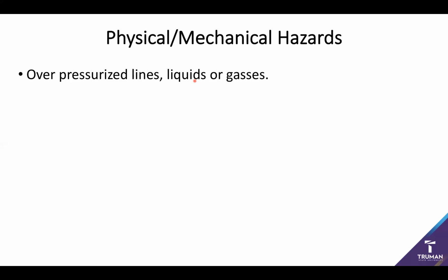Well, it turns out that one of them had been overpressurized and promptly set a spigot shooting 50 feet across the room and left a dent in the opposite wall. So just because something is built in doesn't mean that it can't be dangerous. So watch out if you notice that any line in your lab, liquid or gas, might be holding a little too high of pressure.